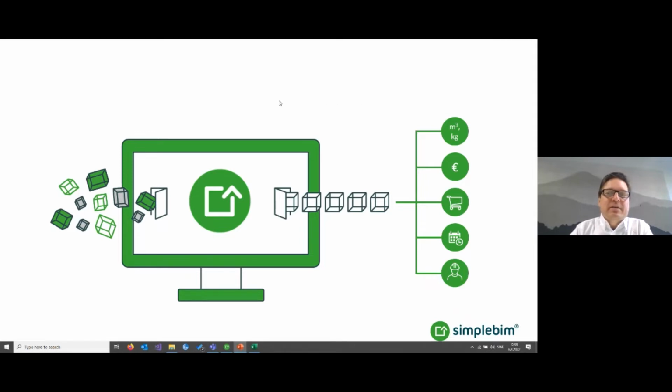And when you use IFC data, then you have the question of what do I need? So in order to do all the things I want to do with IFC, what is the information in the IFC I need? How does it have to be structured? So for example, cost, quantities, procurement, scheduling, construction site, whatever, you always need something. And then on the other side is what you get from the designers, architects, structural engineers, mechanical engineers, and so on. And the thing is that what you need is not what you get. So how do you solve the issue? How do you get from what you get to what you need?